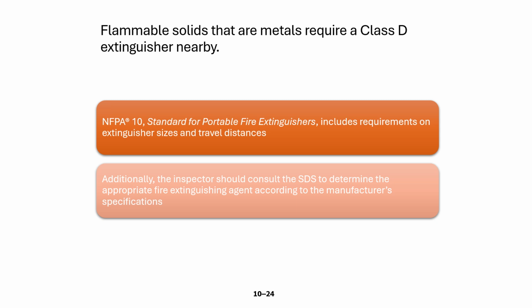Additionally, inspectors should consult the safety data sheets, the SDS, to determine the appropriate fire extinguishing agent according to the manufacturer's specification. You just need to understand that from a portable fire extinguisher perspective, you're getting the right agent, or the most effective agent, given the type of material that might catch fire. So in this case, we're looking at flammable solids.